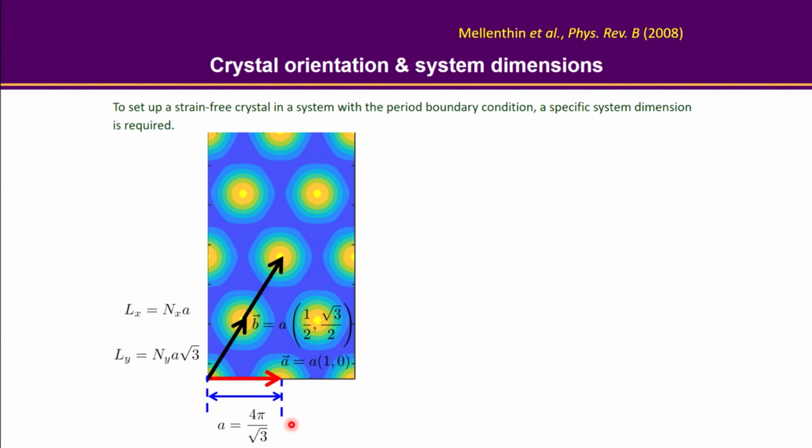But of course, if we want to get the solid-liquid interfacial energy for a different crystal plane, for example cutting from this atom to this atom, because you can always make an arbitrary crystal plane, then I need to set up a system where half is solid and half is liquid. The problem now is, what should be the new dimensions in the x and y direction respectively, so that I can fit this rotated crystal into my simulation domain?